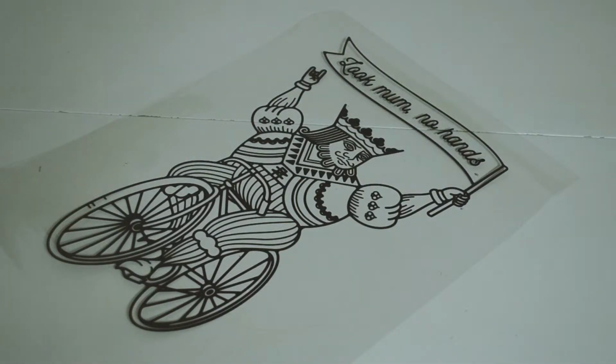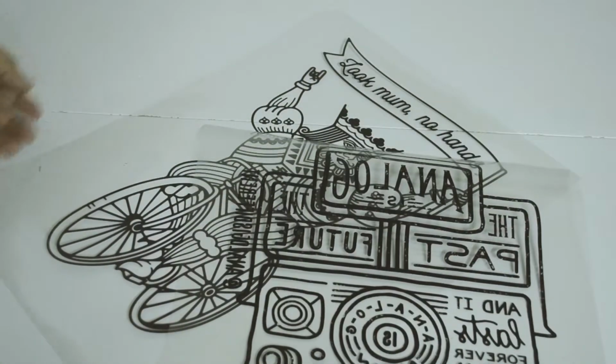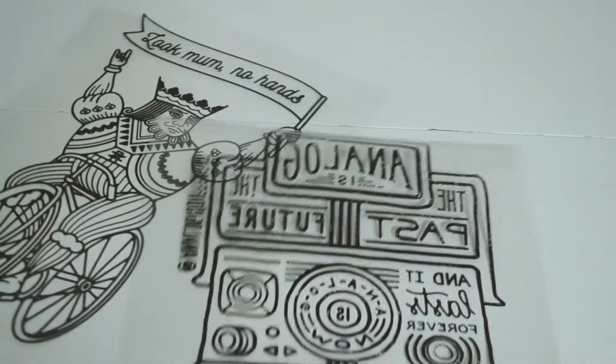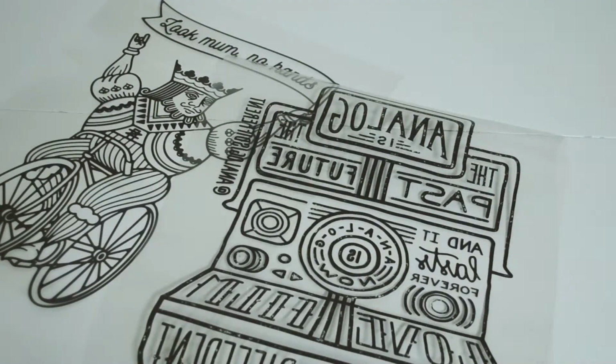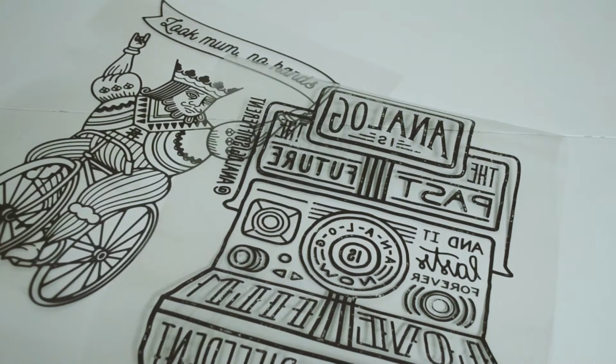As we mentioned, printing off photoliths, especially if you're going to do the printing yourself, is something you should never ignore. The photolith is our printed design on a transparent or semi-transparent paper. We can buy these papers in any stationery store or online and use them in our printer. The design should be black, as pure as possible, although we need to consider that there isn't a black capable of absorbing all the radiations, a true black. So actually, black tones are just very dark greys.